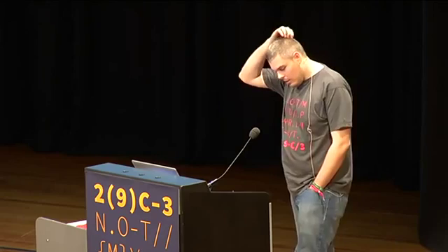Because it's much easier to code the demodulation routine on your laptop than trying to encode it in C540 assembly. Because of course, when you're essentially patching the code of the DSP, you put your own code in RAM, but it's not like TI provided us with a map of what address was free and in RAM and what address wasn't. So we have very little space where we can actually put stuff without breaking other stuff. So we want to really be as small as possible, and that's why it has pretty much to be coded in assembly and by hand.